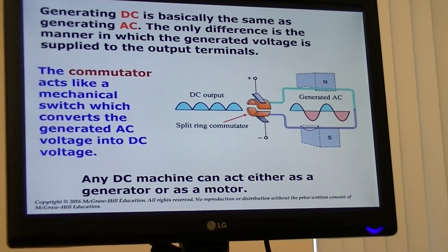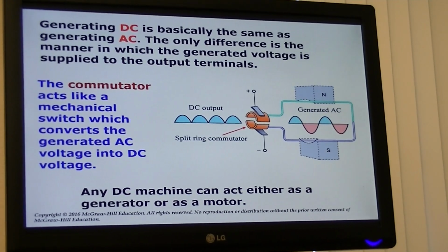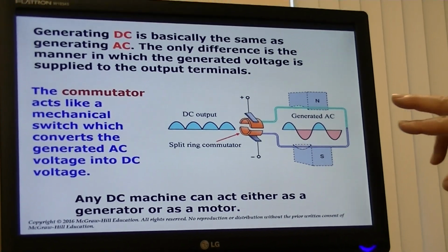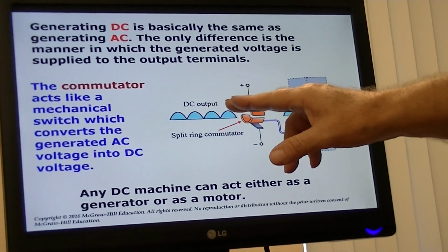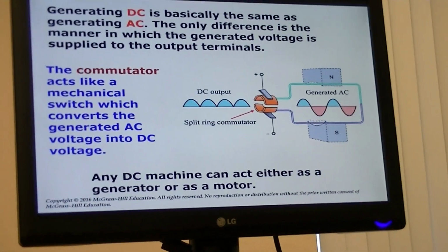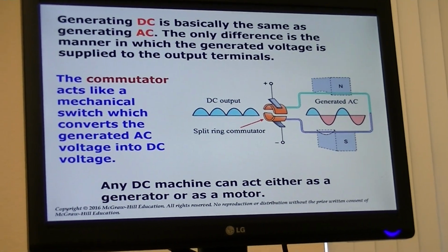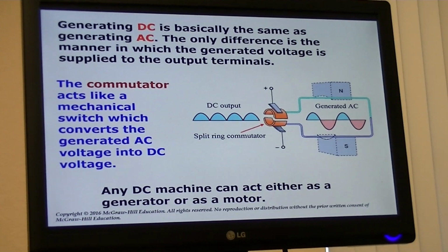However, as we've seen before, you can have additional coils in there out of position with one another. Let's suppose we've got 10 coils and each one is situated around there. Then we would have 10 individual loops all lining up, and by the time you get there, it's darn near a flat line all the way across. So that's generally how a generator makes DC power.